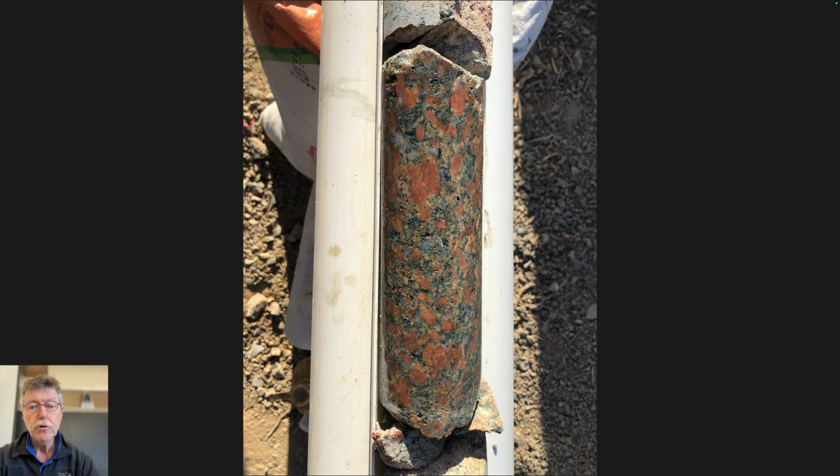We talked about core barrels where you have like a cookie cutter with artificial diamonds placed around it to abrade the rock, and then the rock rises in the tube as the tube advances into the ground. And because there's a drag on the side of the core as it goes into it, it gets twisted off. So any natural fractures there will typically get twisted off just by the torque of the material.